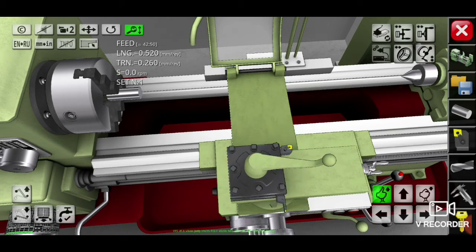If we want to use the number 5 cutting tool, we just simply put this cutting tool in this position. If we want to do grooving operations, we just simply change using the groove cutting tool like this. It's very simple. Now let's take a look at the carriage below the tool post.